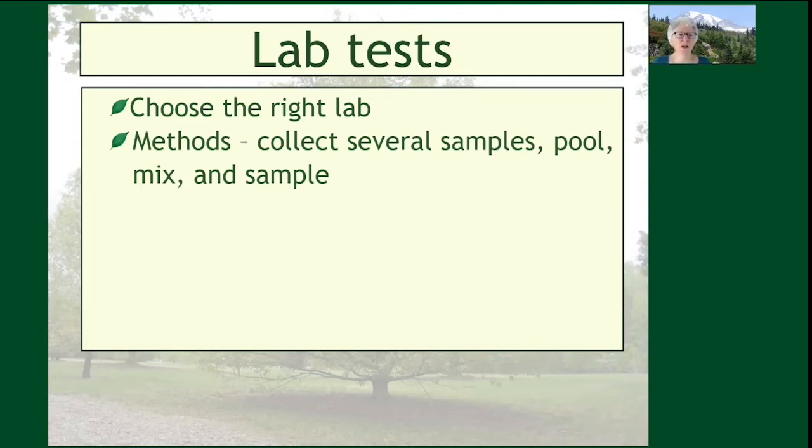So this is a way that you ensure that you have a good mixture of the soils that are on your site. Now, if you're doing more than one site, of course, you have to have different samples and different pools because those are going to be probably different from one another, or maybe not, but it's important that you have those things separate.